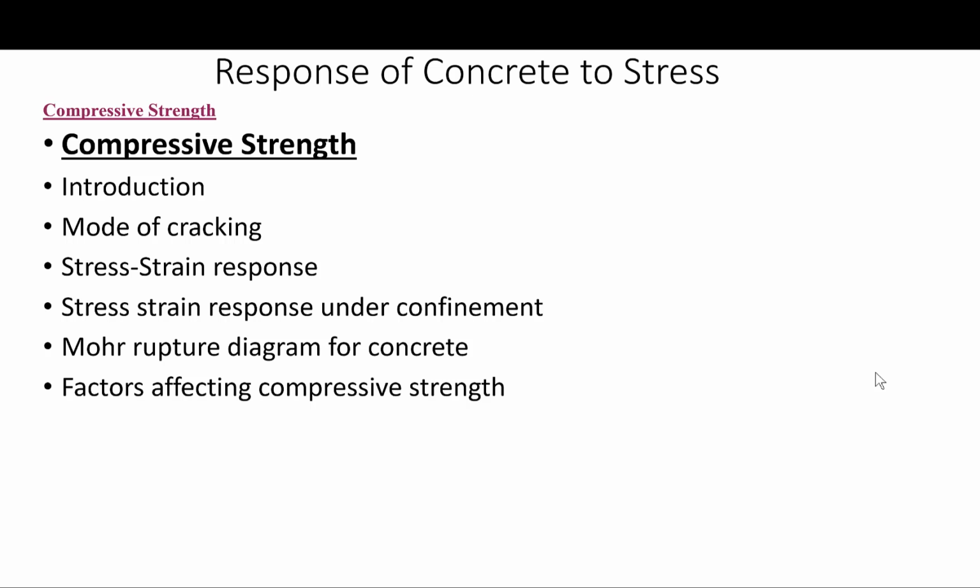The stress-strain behavior of concrete is normally evaluated under a uniaxial compression test, in which a concrete cylinder or prism is loaded along a single axis. The standard test in North America, as we will be discussing in detail later, uses a cylinder with a height to diameter ratio of about 2, loaded between rigid test platens.